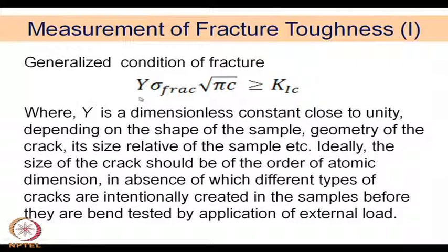Where Y, we have seen it earlier, is a dimensionless constant close to unity depending on the shape of the sample, geometry of the crack, its size relative to the sample size, etc. And ideally the size of the crack should be of the order of atomic dimensions.